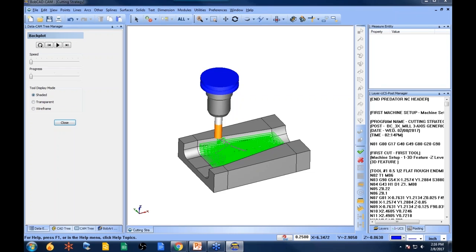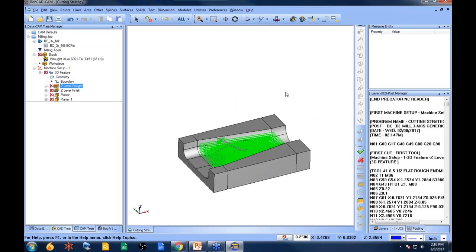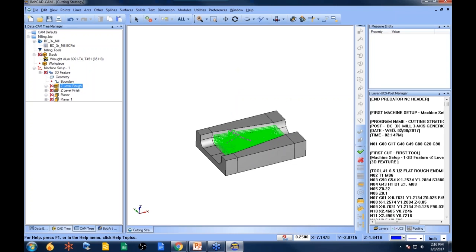How do you pause for each feature for manual tool change? You do the same thing. The features are the features. When you want to pause, you just do it in the post processor. It'll post an M00, M01, whatever you want it configured to, and you'll handle that.